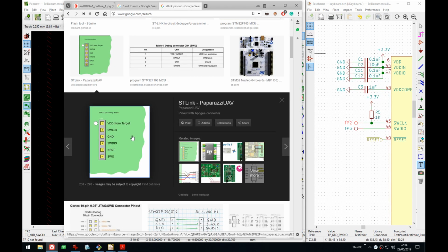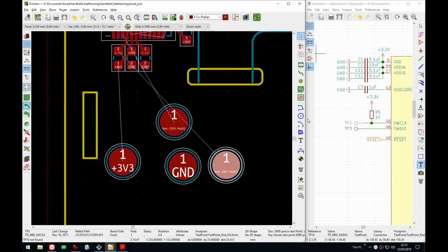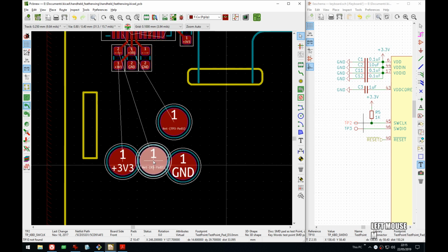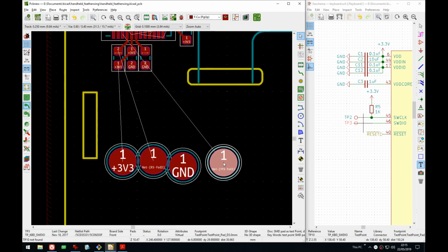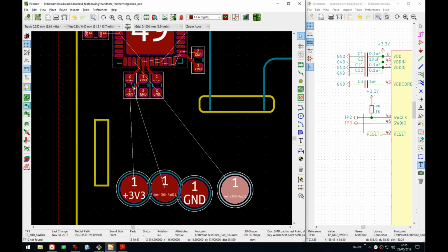So that's usually the pinout I'm striving for with SWD, like this ST-Link, because of the flashing board I have called Xil Debug, which the guys at our hackerspace and I made, and it uses CMSIS-DAP, and that's the pinout we took for it. So I want to have it matching. So it's clock, ground, IO. So clock, this one, and then this one. Which sucks.